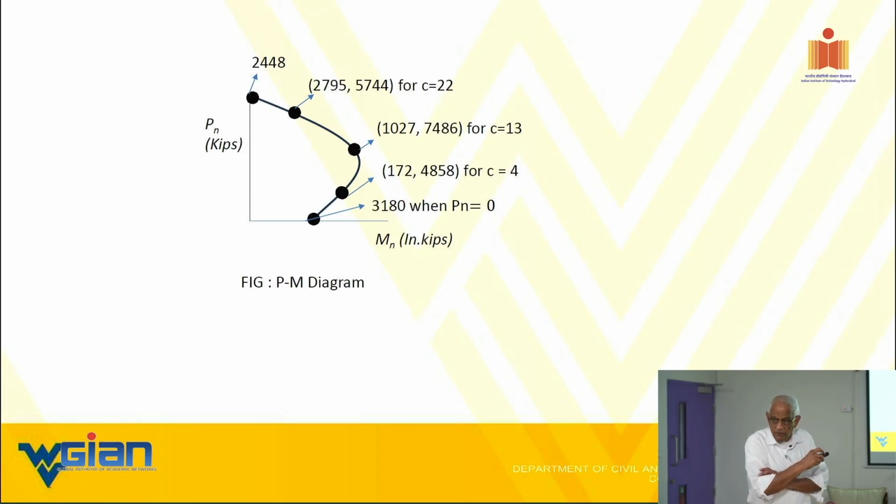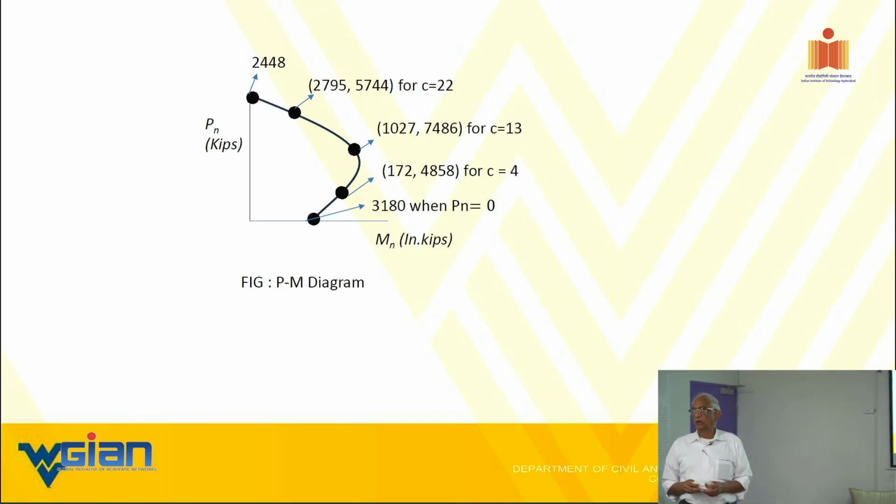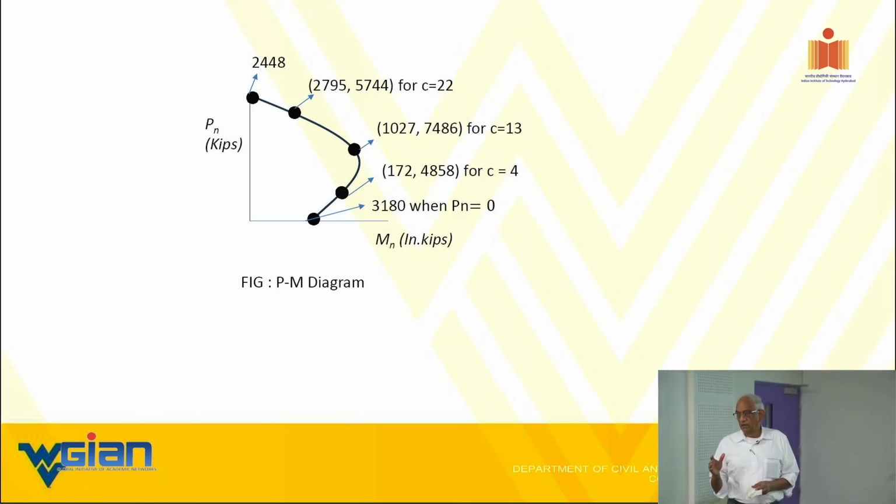Whether or not the loads or the moments induced by combination 2 or 3 are higher than the ones I gave you here. If they are higher, then I'm in trouble. I have to redo it. If they are lower, coming from the applied loads, then I'm in good shape. So that essentially concludes how you check whether your column is satisfactory or not.